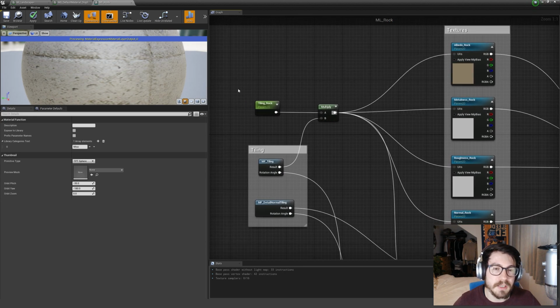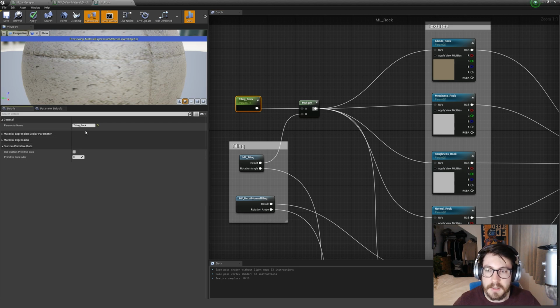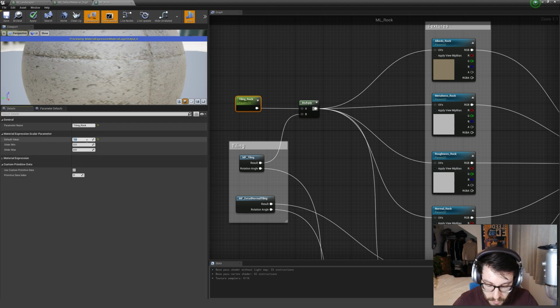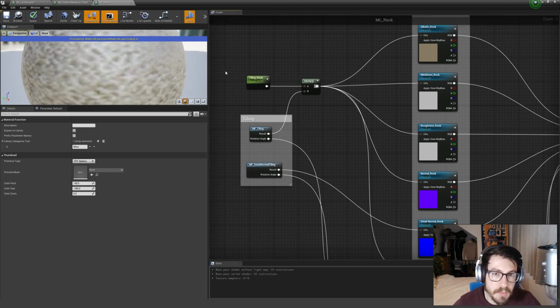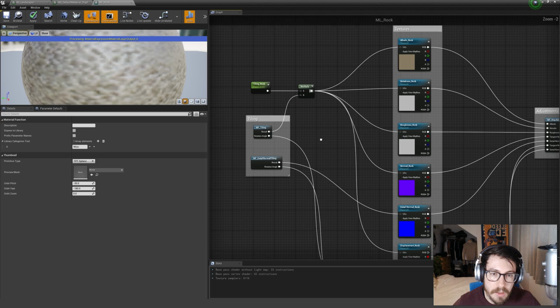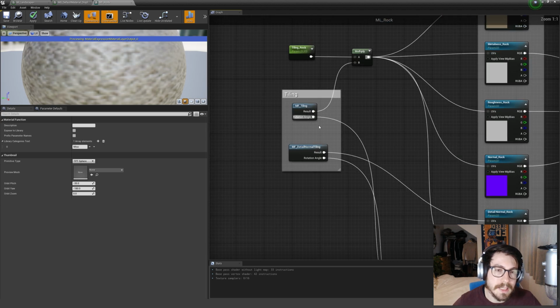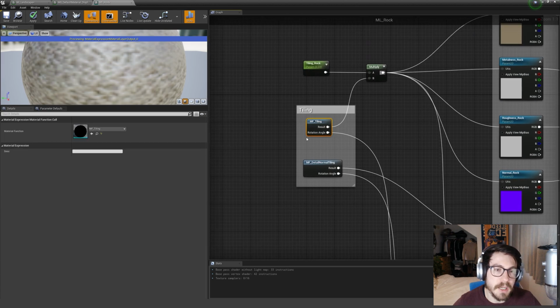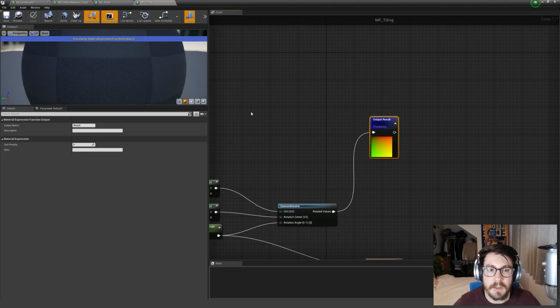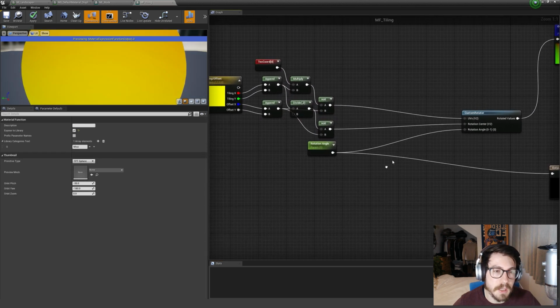I know for a fact that the Quixel materials in landscapes need a tiling that is more about 0.33 or something, so that they look good. So I can already put 0.33 in here as a value. If we would want to rotate these as well, which we might want to do, we would need to change this tiling function a tiny bit. I'm going to do this now. You don't necessarily have to if you don't want to rotate your landscape materials.